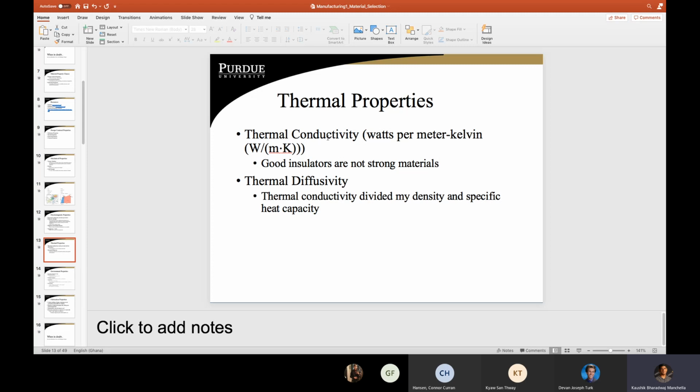It's thermal conductivity. A prime example would be a situation where one of the teams was making playground equipment. Selecting stainless steel, for example, a material which has very high thermal conductivity, would be bad in this situation because the playground is going to be outside, and when it's very hot and kids sit on the swing set, it's going to burn the kid. So in that sort of situation, you would consider thermal conductivity.